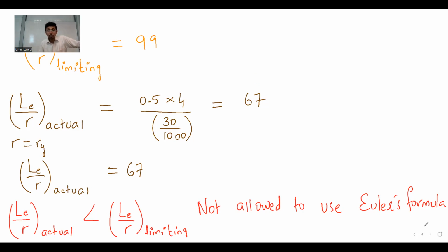Mitch, the answer to this question right now, what happened is that I understand your question. The problem is that if I start going for the actual answers of this question, it will take us to a different route. I will have to use one more formula, Rankine-Gordon. I'm not using it. So what I am writing here is that if this has to fail, it will not fail under pure buckling.